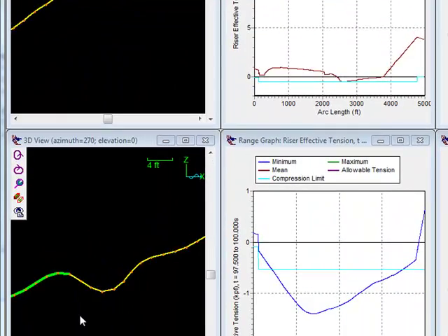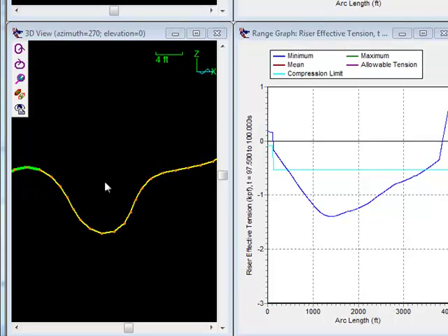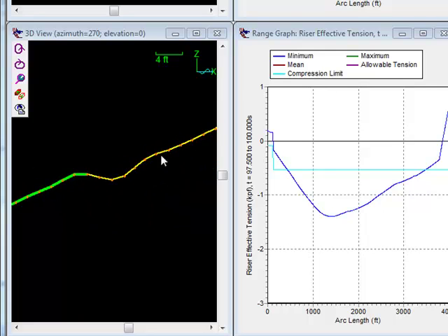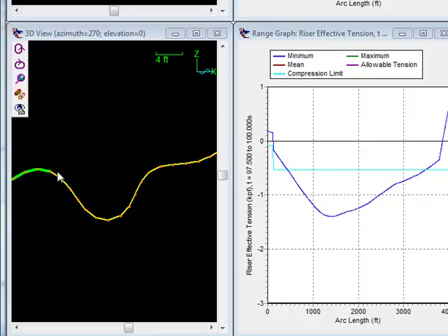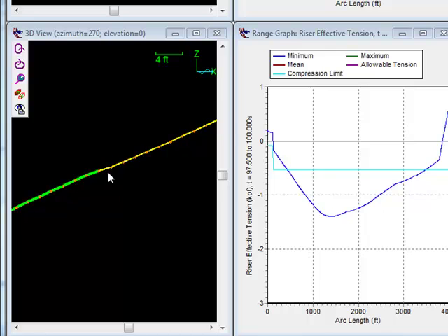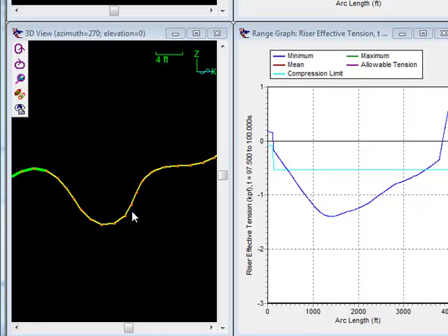Down here we can see the point where the green indicates the floated section begins and the bare section on upwards to the buoy. The bare section is trying to slide down like a worm in a hole, meets the floated section, which offers significant axial resistance to sliding in this direction, and we see a very prominent buckle wave or compression wave forming.